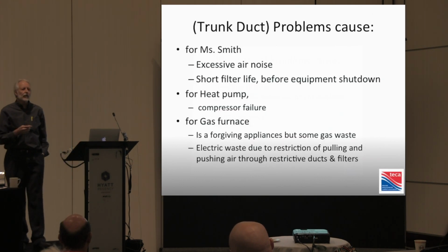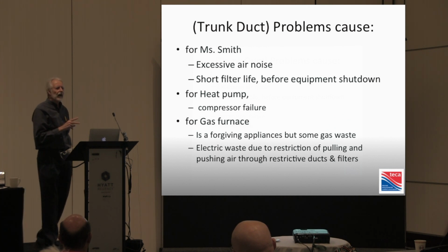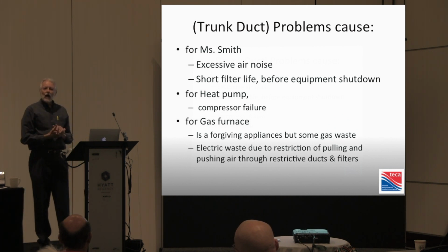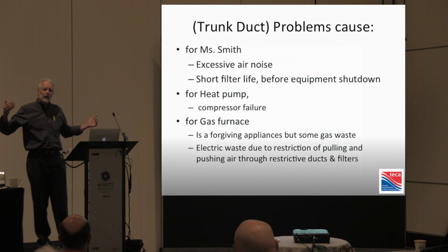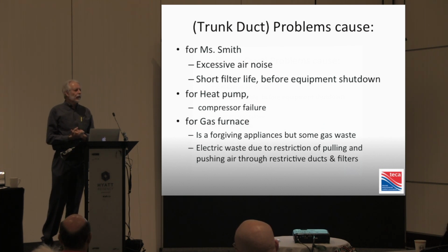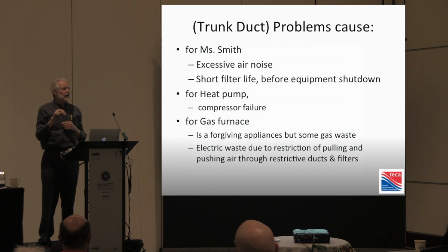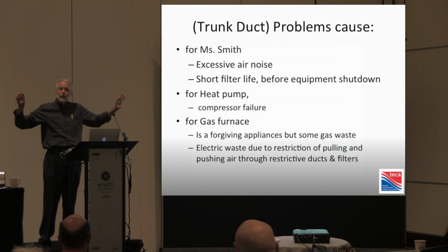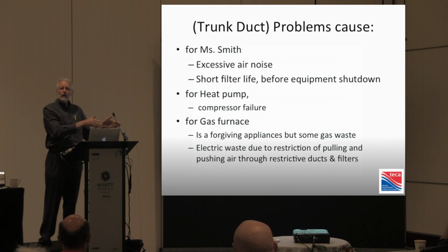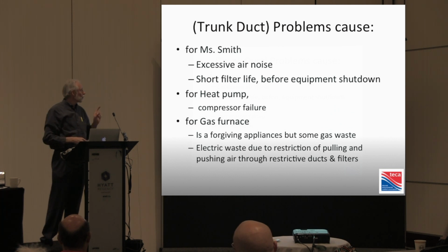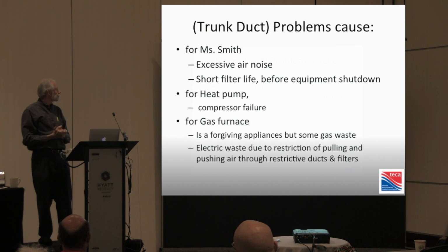I mentioned the ductwork systems then. There are 2 areas of concern to do with the duct. Number 1 is the trunk ducts, and number 2 is the branch ducts. Then, of course, leakage. What is a trunk duct? A trunk duct is the duct that usually goes the full length of the house. It's usually the big stuff, and it's defined as a duct that's big enough it's got branches coming off it. So when you see a branch coming off the side or top of a rectangular duct in the basement or a crawl space, that big thing is called a trunk duct, and there's 2 parts. There's a cold part and there's a hot part. From the trunk, then we have what are called branches, and I'd like to show you about 10 slides to show you about trunk ducts.